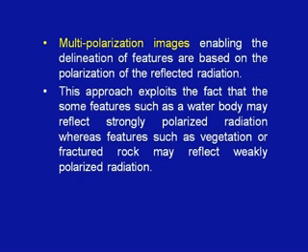Next is multipolarized images. This enables the delineation of features based on the polarization of the reflected radiation. This approach exploits the fact that some features such as water bodies may reflect strongly polarized radiation, whereas features such as vegetation or fractured rocks may reflect weakly polarized radiation.